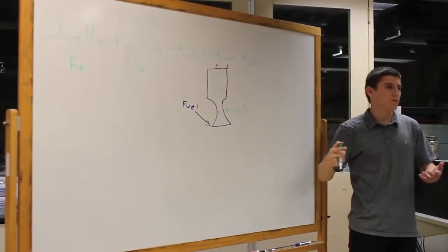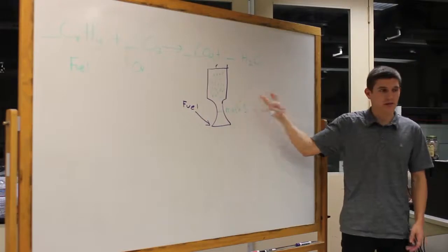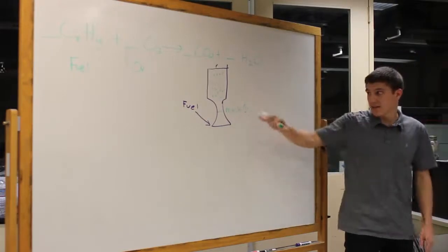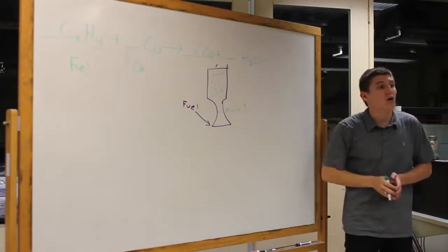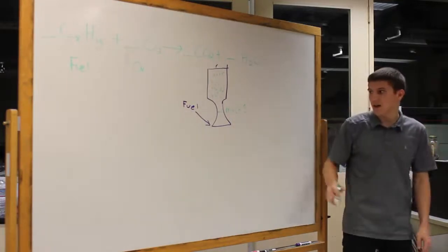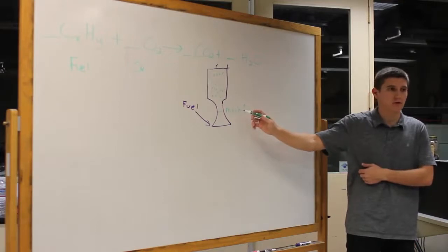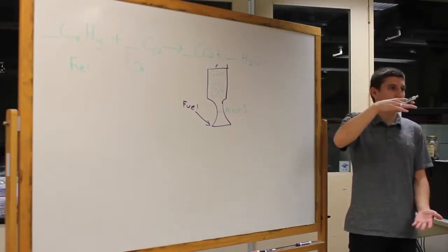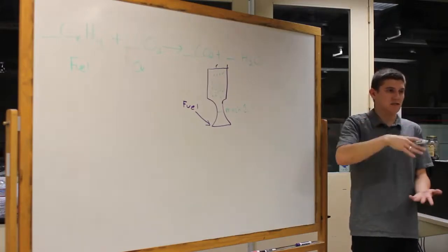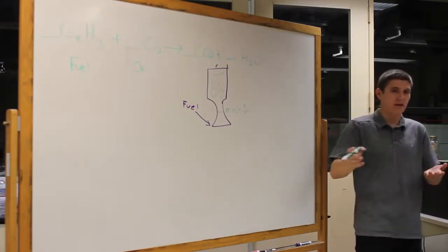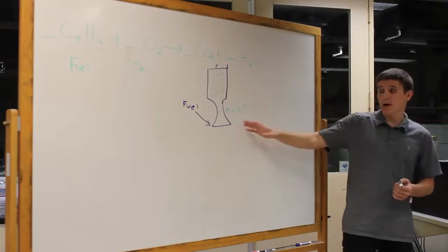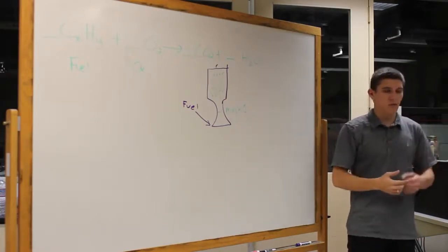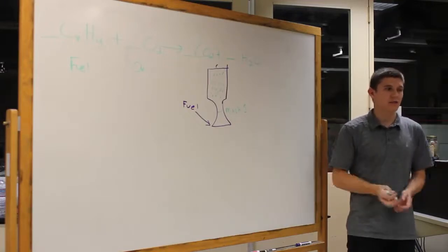And when you hit compressible flow, you go from incompressible fluid, like hydraulic oil, imagine it's really slow moving, to this gas, which when it expands will increase in velocity because of the way compressible flow works. Usually if you have a container and you increase the area, the velocity of the gas decreases because there's more room for the gas to move, it can slow down and not hit each other as much. With compressible flow, once you pass Mach 1, everything is inverted. If you increase the area, you increase your velocity.